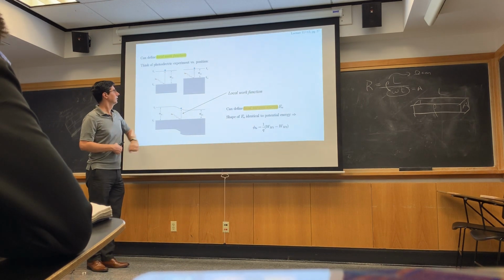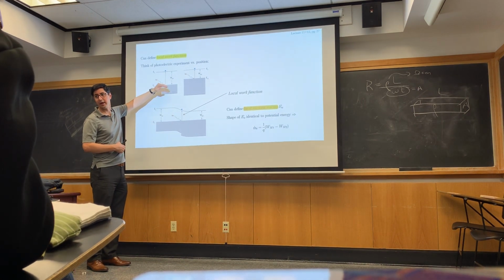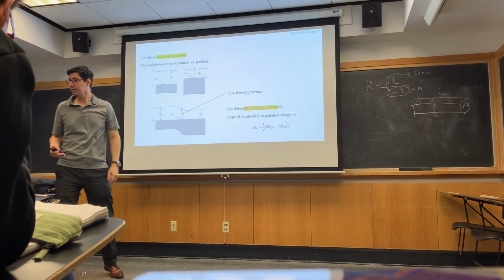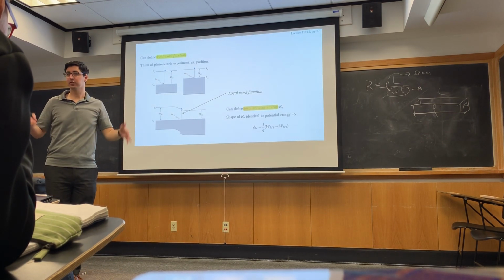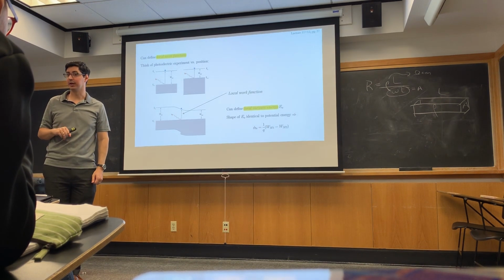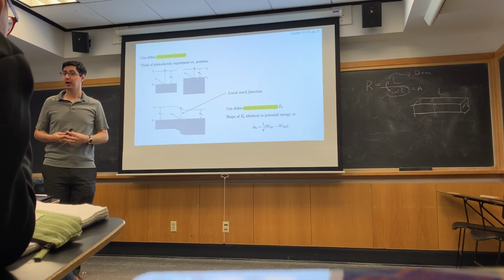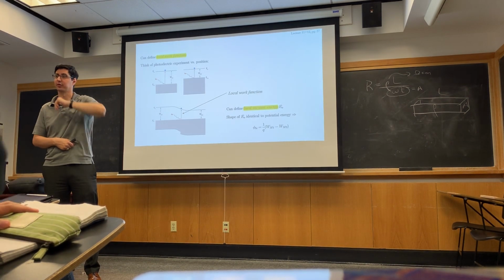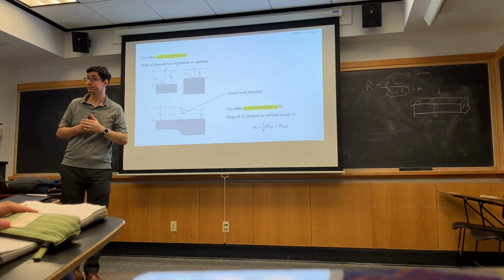And the average location of an electron is going to be at the Fermi level, right? In a semiconductor, we don't actually have states at the Fermi level, but that's kind of the average location where I would add an electron, if you think about it, right? In a neutral semiconductor, I would on average add either in the valence band or in the conduction band. So the Fermi level's in the middle of the band.